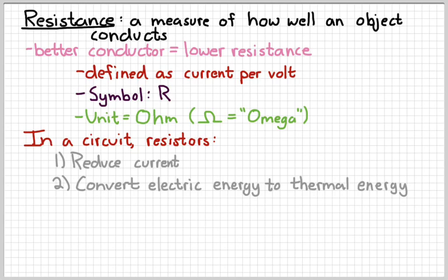So coming back to the measurement of current, what affects it, the relationship between all these variables is referred to as Ohm's law. The greater the voltage, the greater the current; the greater the resistance, the less the current is. And so this is a really useful law for solving problems and analyzing circuits.